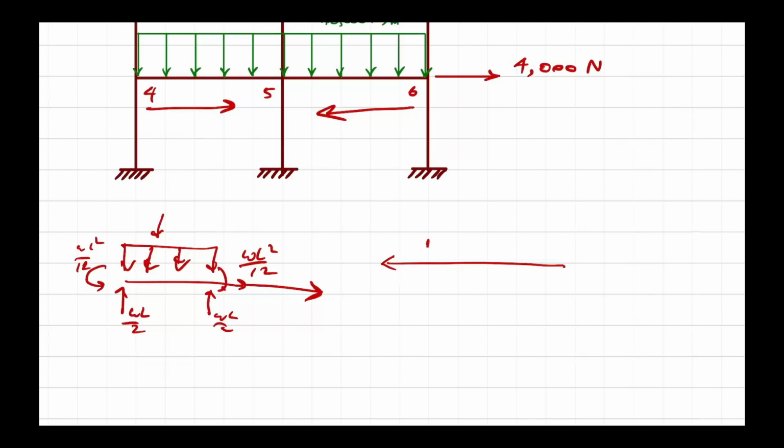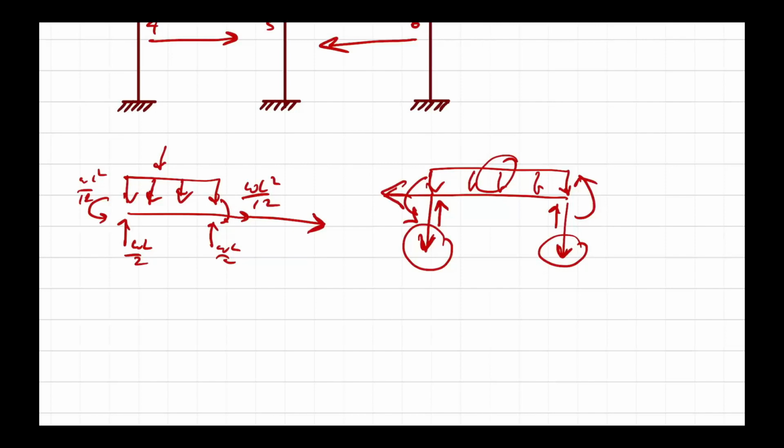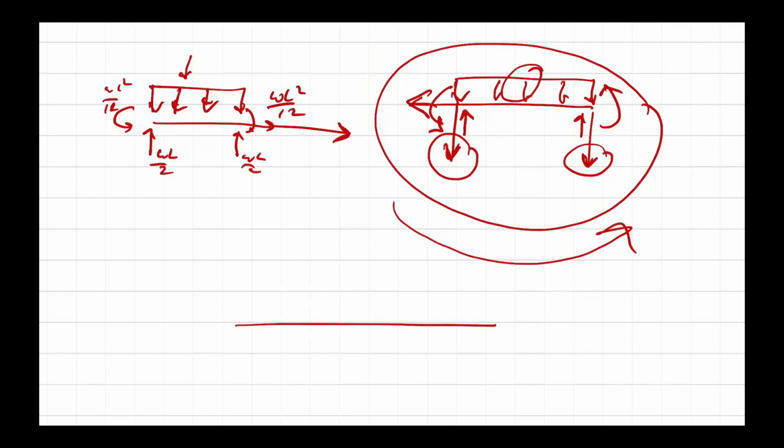Whereas in the system there, as the local coordinate points towards the left, you got to turn it upside down, because the positive sense of fixed end reactions follows the local coordinate. Positive goes like this, and positive rotation goes like this. So here is what you obtain as a fixed end reaction to this load, but it is in the opposite direction to this positive sense. Or basically, if I just rotate this picture and make it go like this, it's going to look like the load coming this way.